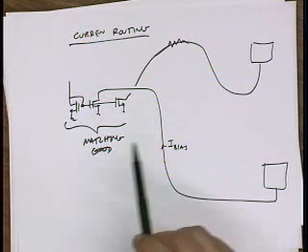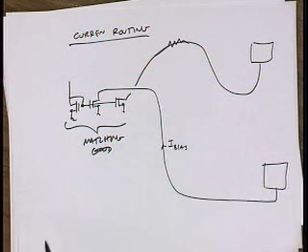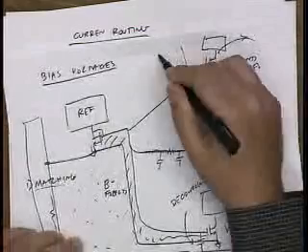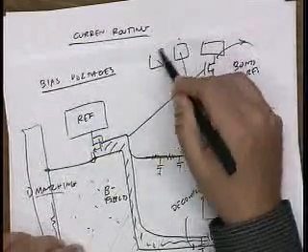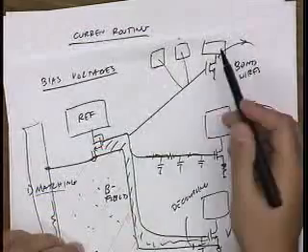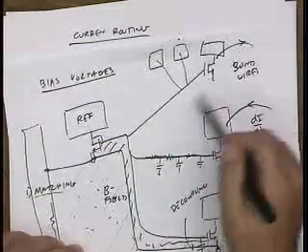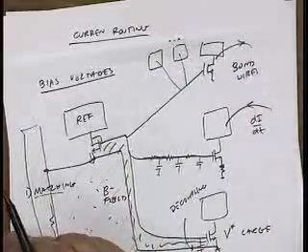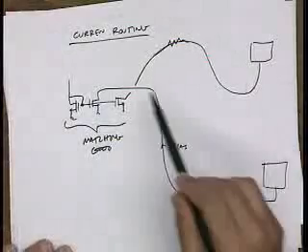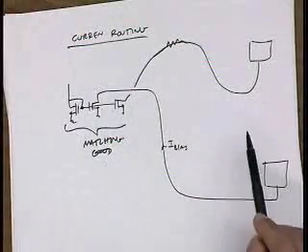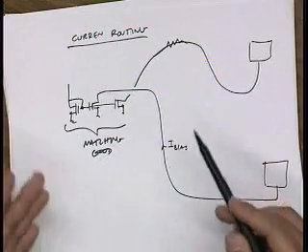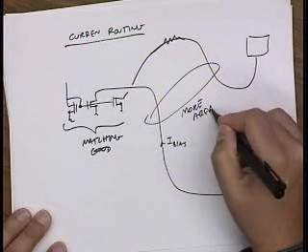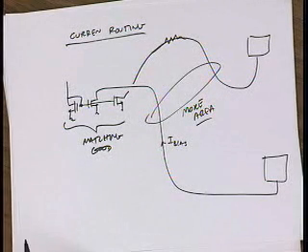Well, one thing is I can't share these bias currents, right? With a bias voltage, at least if I wanted to, I could have shared this voltage with a bunch of other blocks and basically just had one wire going out there. Of course, that makes this more susceptible to interference, because if one block has noise, it couples to the other blocks. Here, though, I have to route currents to every circuit separately. It's not a voltage that I'm routing, it's a current I'm routing. And so this may involve a lot more wires, right? So more layout. Let's say more area. What's another disadvantage of this approach?